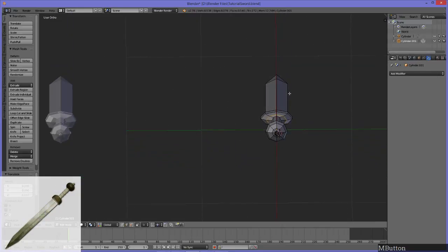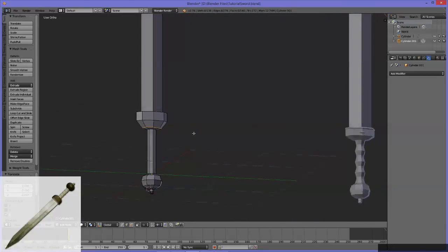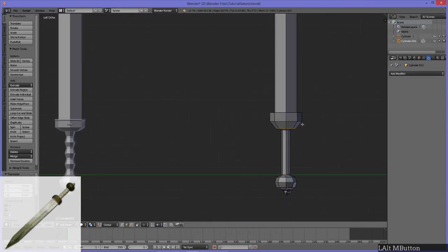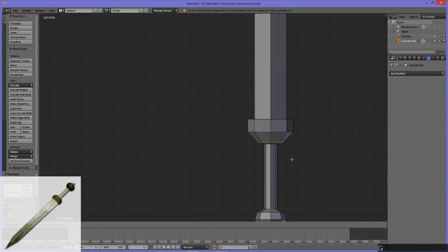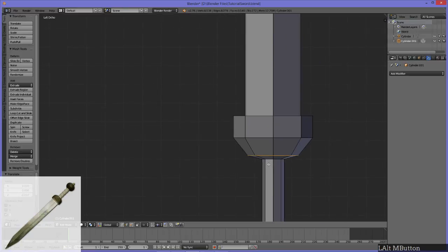You can also scale that up if you want to. Another way you could do that, and this is one of the tricks I like to use, is you hit G twice and it'll move along the other two edges, slowly becoming the other edge. What we can do is, let's go to escape. So this is where we were. We can now do G twice, move this up, and then hit G once and Z, and now we've got a thicker edge.